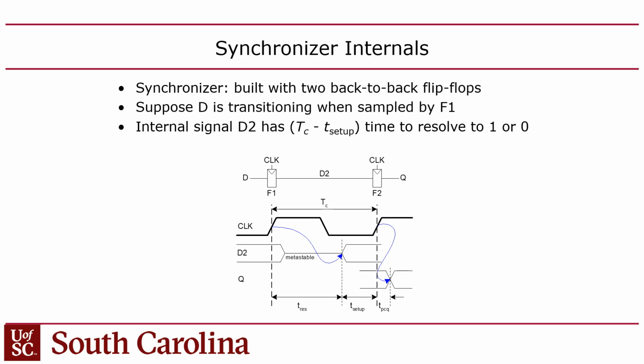You just put those on places where there's that chance. Yeah, wherever you have an input. Inputs. Yes. I'm not sure about this, but I think the FPGA input buffers have built-in synchronizers. I think. Never confirmed that. So it's not something you have to add. I think it's built into the I/O resources.